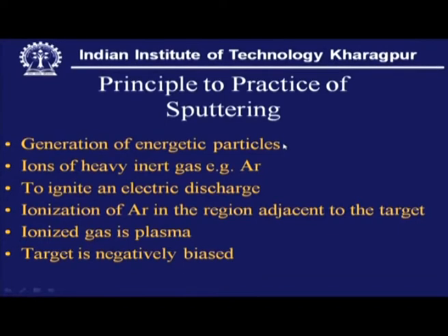This sputtering is conducted in a closed vessel or chamber which is evacuated, and inside that chamber one has to generate energetic particles, which will be the ions of a heavy inert gas like argon.